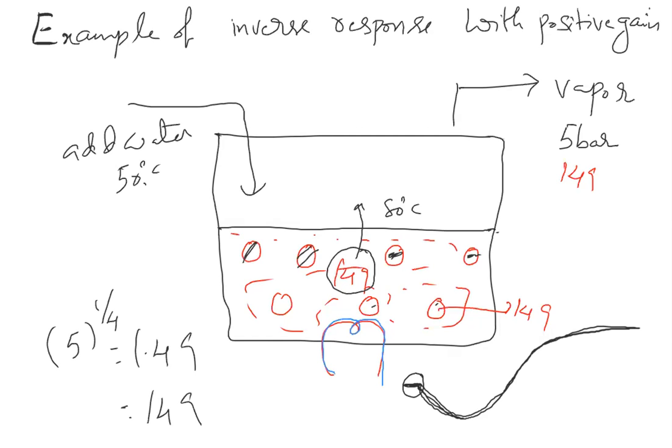So that is why level control of a boiler is extremely important in the plant, because if a boiler shuts down, you have to take the shutdown of most of the plants in a refinery, because most of the plants have boiling steam as a heating medium. That is why even in the boiler, level control is extremely careful. That is why when you apply the level controller, you will do feedback and feed forward controllers together. Because when the level decreases, there is a trip of the boiler.